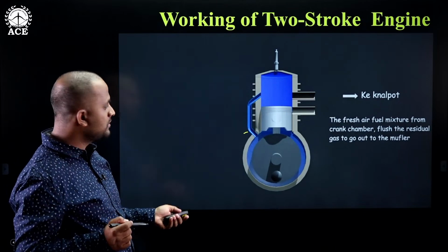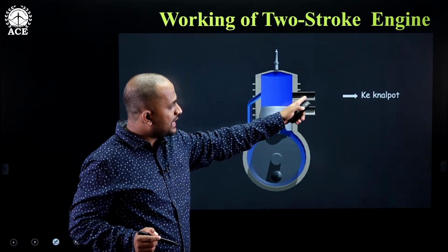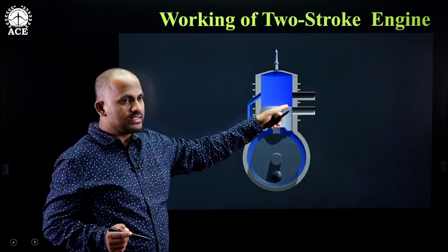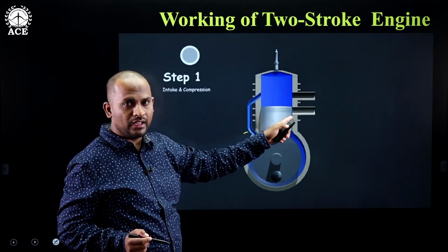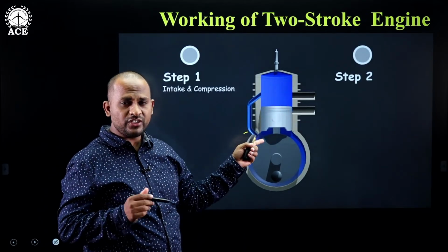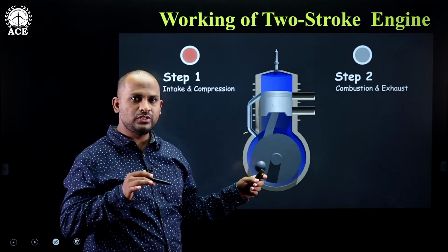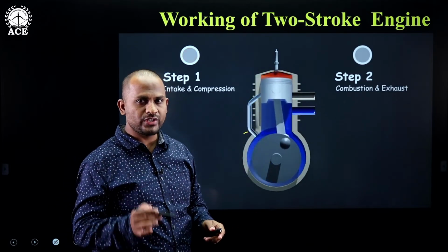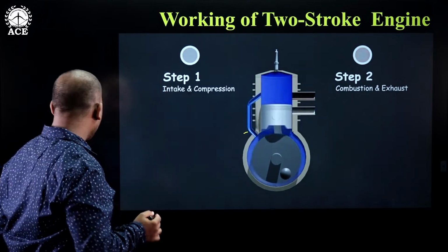Now here one point is important, that is when the exhaust gases are leaving the cylinder from one side, on the other side the fresh charge is entering. That is, this fresh charge will try to push the exhaust gases outside. That process is called scavenging process.